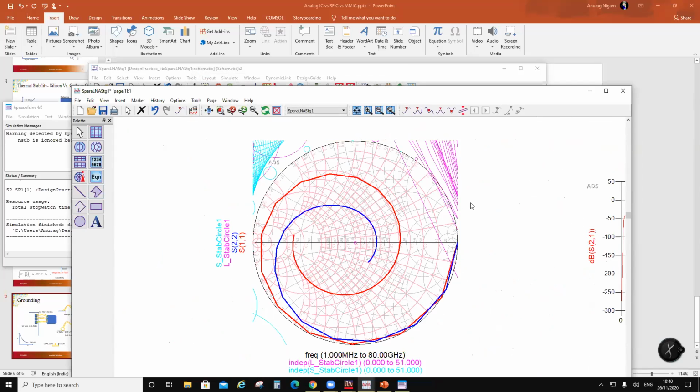See, whatever you do here is small signal. Now, we are not supposed to look at a power amplifier from a small signal point of view. It may be stable at small signal, but usually when the device compresses, S12 drops. When S12 drops, the feedback is much stronger, right?